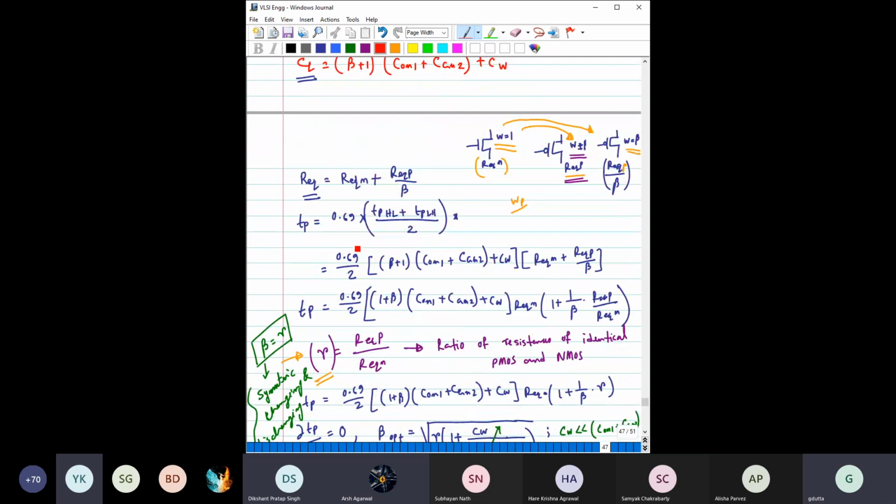Sir, I had a doubt: what's the condition that we aim for while designing a circuit, the minimum propagation delay or the symmetric one? That again depends on your design problem. Sometimes even the propagation delay does not play that much role, but the power will be the most significant parameter. So this is between what you get and what you lose. Okay, sir, got it.